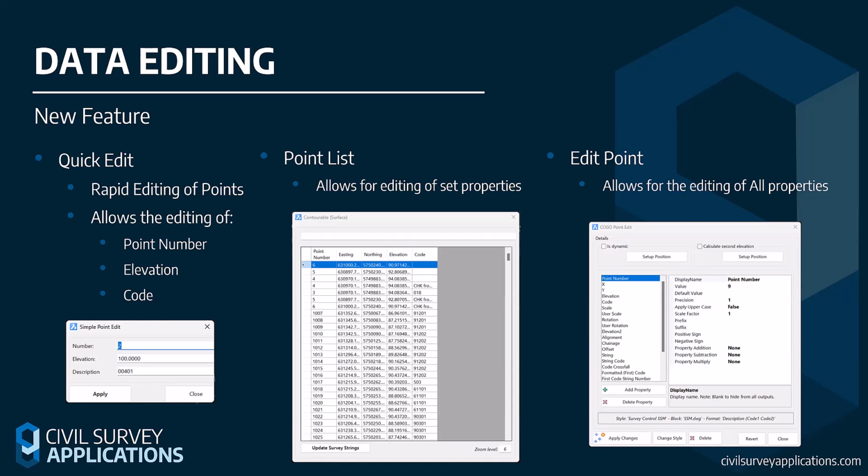If you're wanting more information and you're still wanting that rapid code editing, I recommend having a points list. Points list allows you to edit any set properties that have been set for the point. So by running this up, whatever's been set using point styles, point properties, any of that can be seen here, and you're able to edit it as needed. It also gives you a list of all the points based on point groups, and you can filter these out as needed. So it can be a very powerful tool for this.